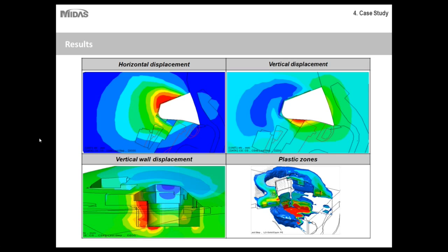For those of you who are curious what tool was used to simulate this deep excavation problem for the foundation and the construction of the Odeon Tower, let me share the software name with you. It was Midas Civil, sorry, pardon me, it was Midas GTS that was used for the geotechnical investigation and modeling the full-blown finite element model in 3D to estimate the horizontal and vertical displacements and the forces in the members.